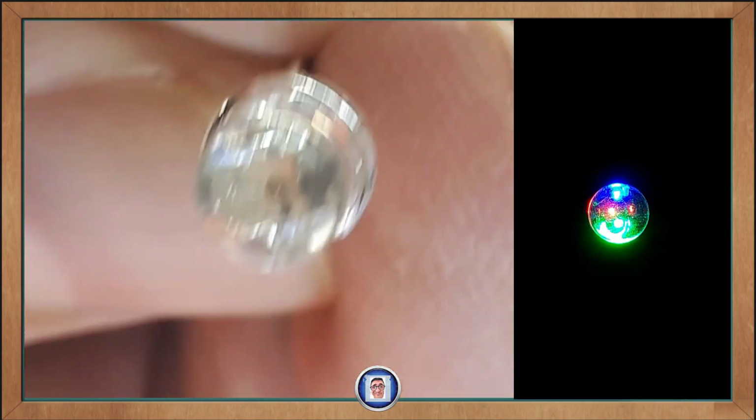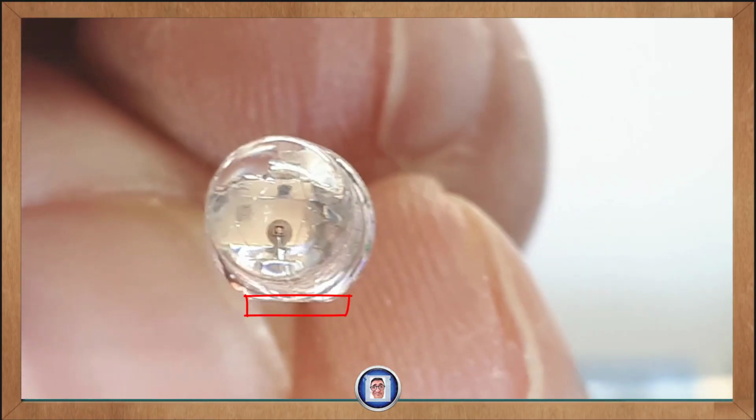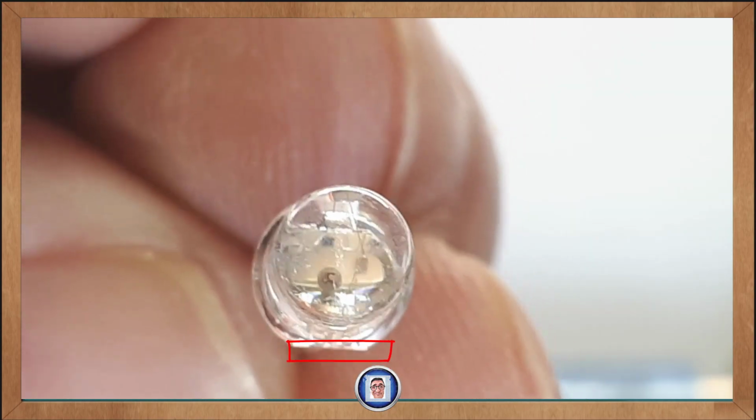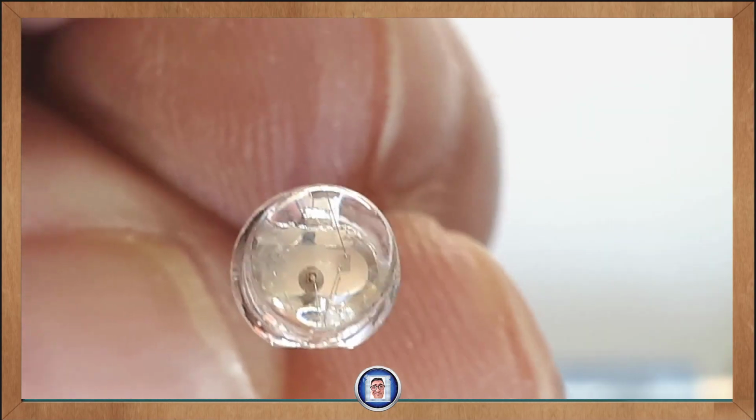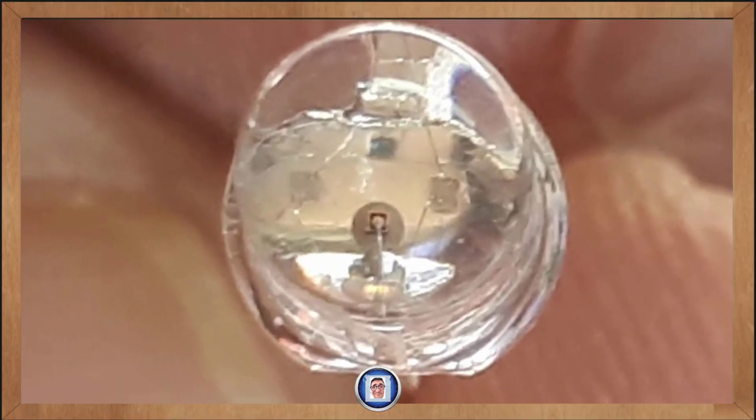Now, if your LED has the leads colored or trimmed, you can still determine the orientation by looking at the flat side of the case. Here, that indicates the red LED side. And if we have a closer look, I will show you where all the LEDs are situated. We know this is the red, then we have the green one, and lastly, the blue LED. This one here is for the common.